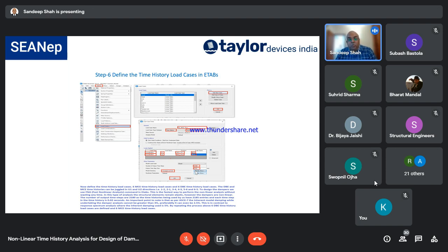Okay. Now when we saw the characteristics of the time history, I made you note that the number of points is 2182. So I'm telling ETABS that it needs to run the time history for up to 2180. And I'm also telling ETABS that the time step is 0.02 seconds, right? So this is because that's what my time history is.